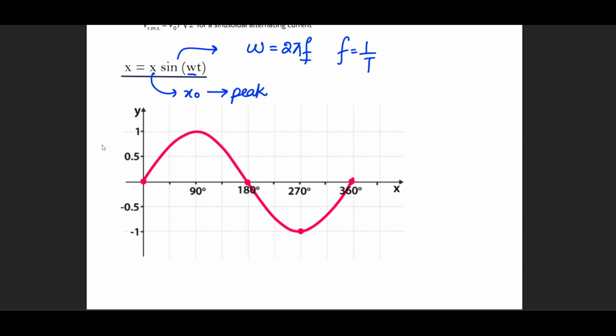So if, for example, the peak value of this function was, let's say, 325 volts, for the sake of voltage at least, then this function will turn out to be 325 sine of omega t, whatever omega may be. So let's say that the frequency of the signal is given to you as 50 hertz, that is what the Pakistani standard is. If this is how it's given to you, then how are you going to write down this equation?